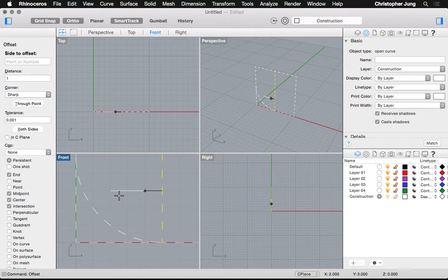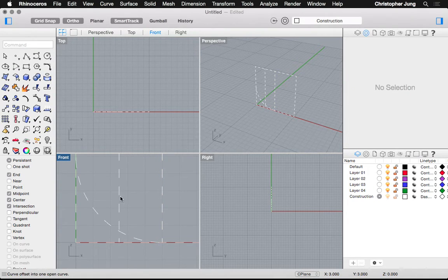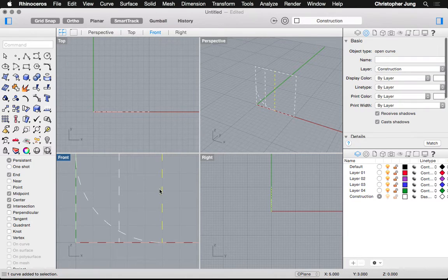So you see this vertical line that I have in the center. I want to offset it, not all the way to the end, about halfway. So I'm going to offset it by 2.5 centimeters. And then I'm going to click, and then you have it offset 2.5 centimeters. And I clicked the direction that I wanted to offset. So this line here was offset to this line.